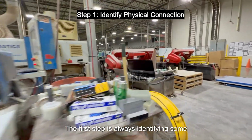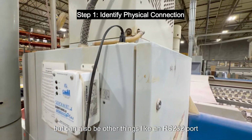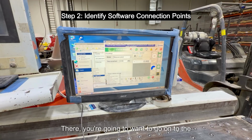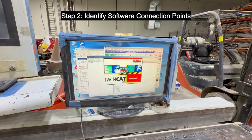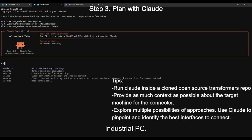The first step is always identifying some sort of physical connection point for the machine. Oftentimes, this is some sort of Ethernet LAN port, but can also be other things like an RS-232 port to communicate over serial. From there, you're going to want to go on to the equipment and actually identify any software that's running there. In this case, we have a TwinCAT 2 Beckhoff PLC running on top of this industrial PC.